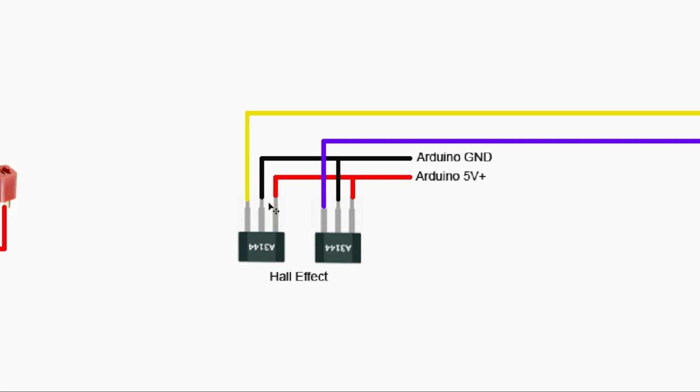So again, I have connected both to 5 volt, so you can connect it together, and then to the 5 volt, and then 2 to the ground. And then the other 2 will be to the pin, this to the pin, this to the pin itself. So again, if you have two Arduinos, you don't see any resistor. I pulled out the resistor that I would connect to the pin itself, because I'm using the internal pull up.